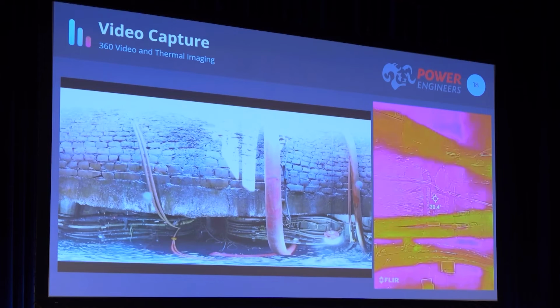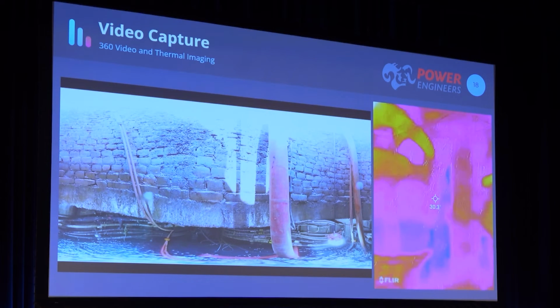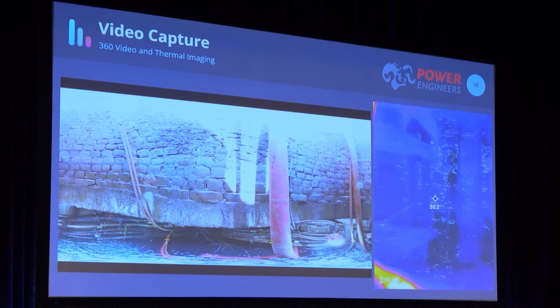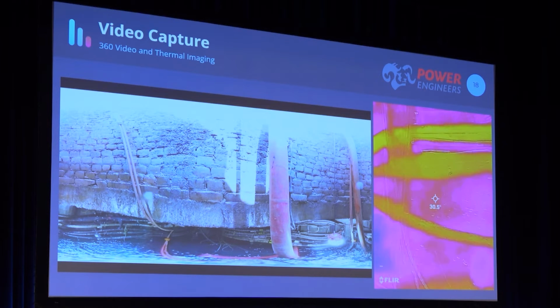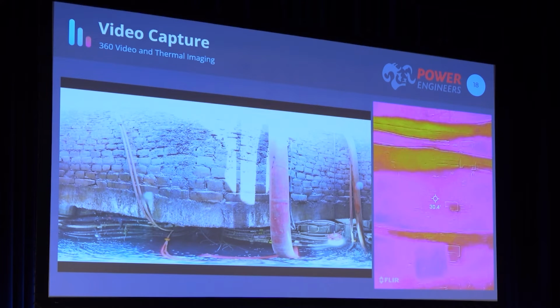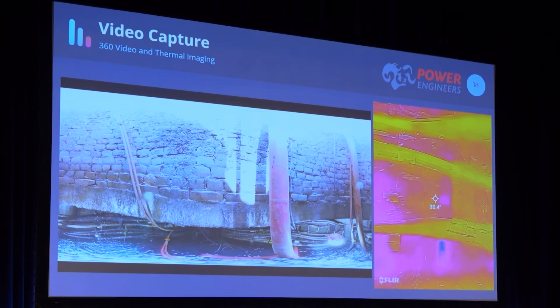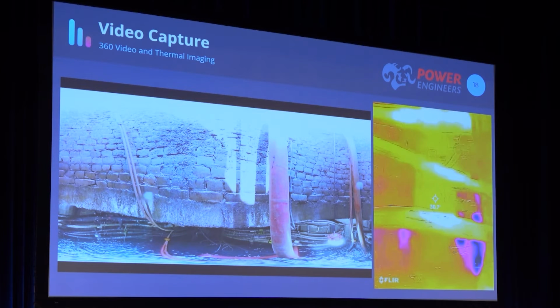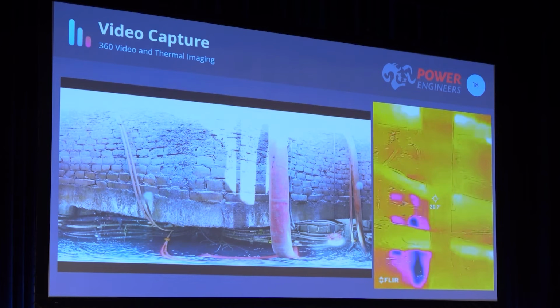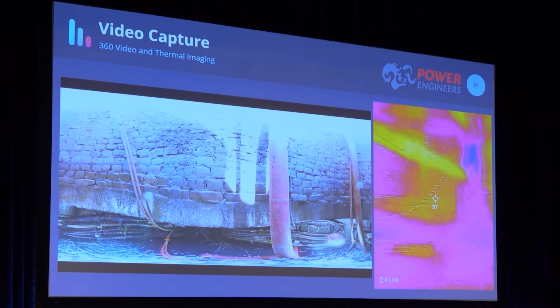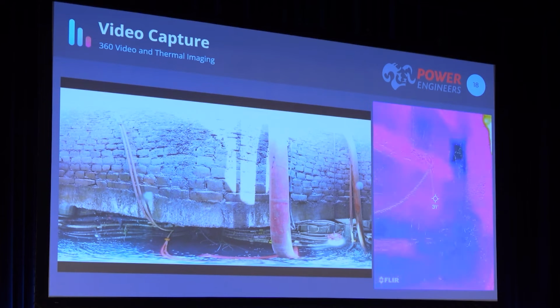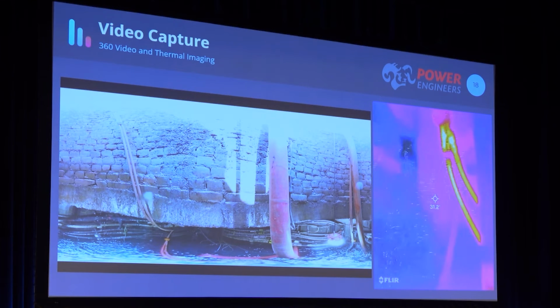Effective traffic control measures are vital, especially in a rural setting. And everybody needs to wear the proper PPE, reflective vests and things like that. Sometimes you get variable depths of the vault, so you have to do assessments for each vault. And the presence of water, obviously in this case, was there, but raw sewage was also a hazard in this case. There were some structural integrity issues to consider. You're lowering ladders down into a slippery, wet floor, things like that to consider.